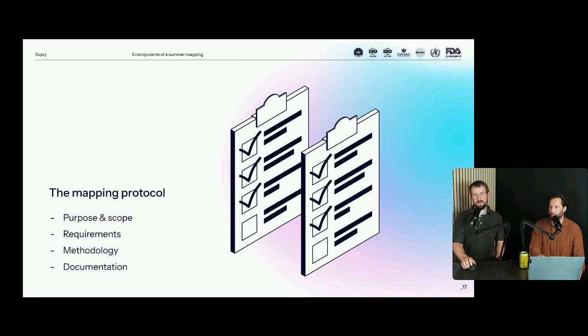And then there was a question again, Mustafa, does the duration of mapping correlate with the size of the space being mapped? Really good question. It does to some extent. If we're talking about a large warehouse, we talked about summer and winter mappings before, there will definitely be variations in terms of what we call external influences. That's sunlight, the lack of sunlight, or very cold weather. So when your facility is very, very large, some of these dynamic influences will only show after longer periods of time.